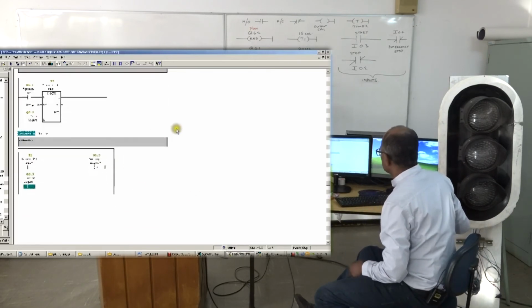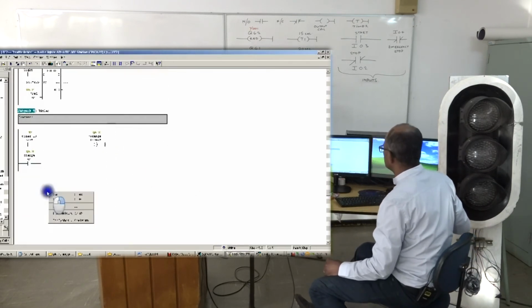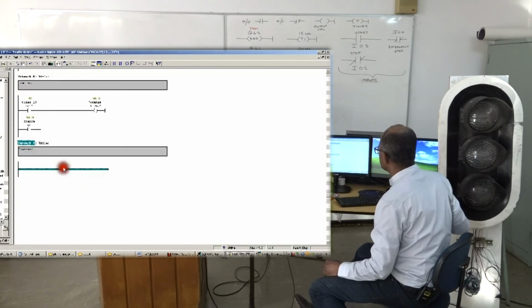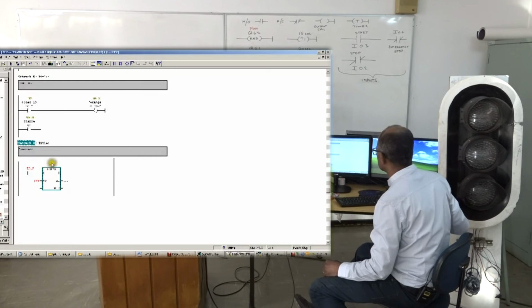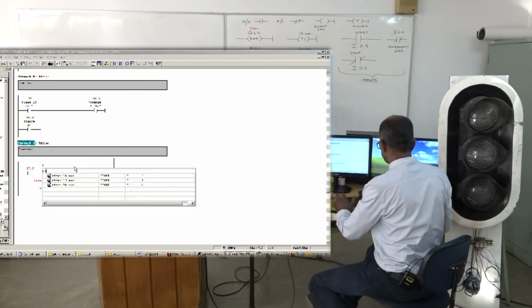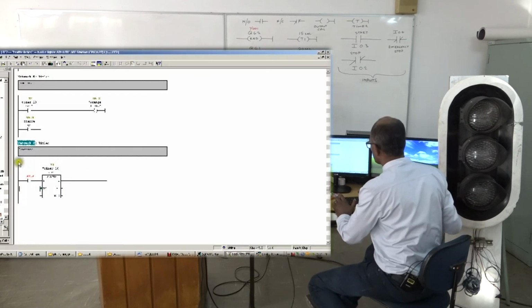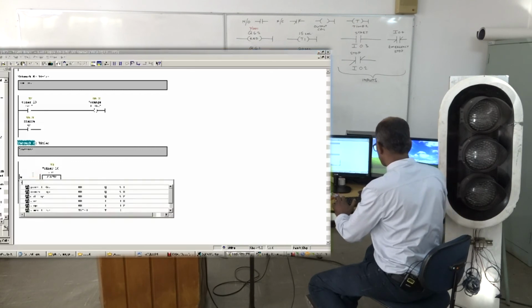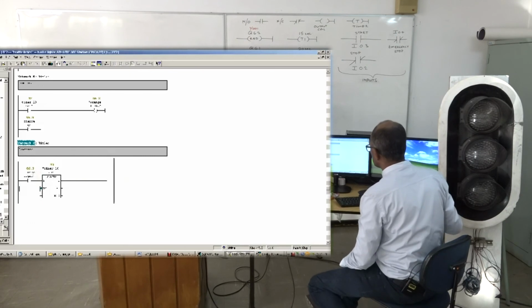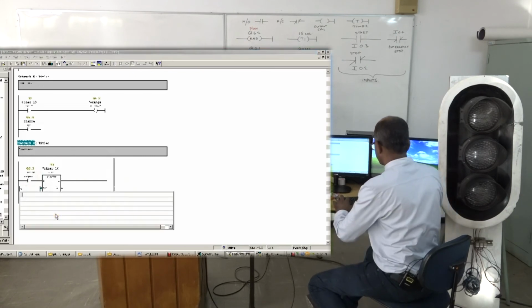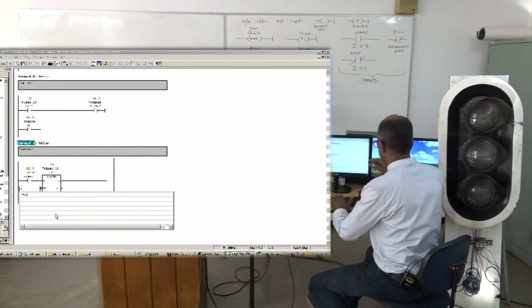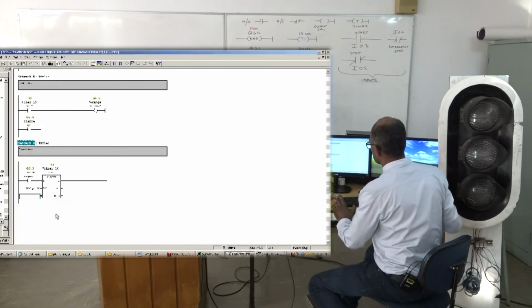Okay, but remember now, we said that the process has to be repetitive. That means I don't have to go and repress my start button for the sequence to continue. Remember, we discussed earlier on the OR function, where we said either switch A can start a motor or energize a contactor, or switch B. And we said those switches have to be in parallel. So I know that after timer T3, I can restart the sequence.